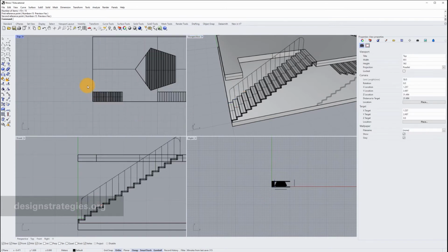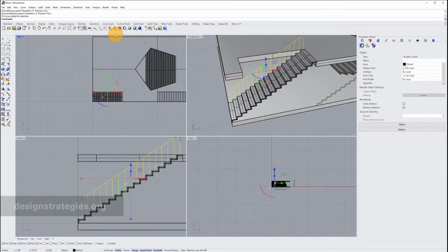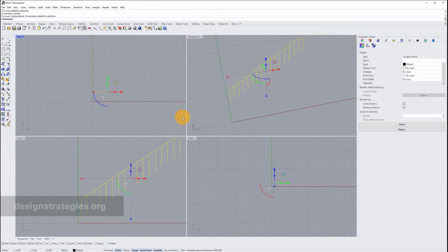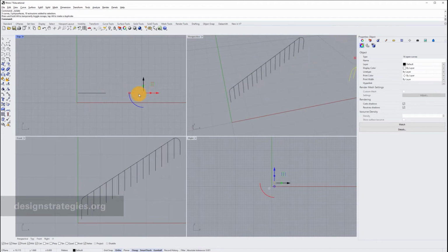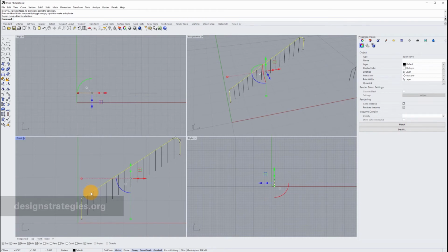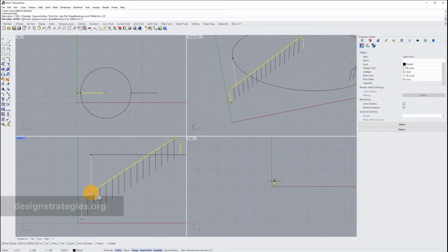Okay, we continue working on the banister. I just select this, and I just go into isolate selections. And we want to have a look what kind of design variations we can do. First of all, this one can definitely get something like a pipe. And I just enter a radius of, I don't know, 0.5 centimeters, and this means it's a really thick one.